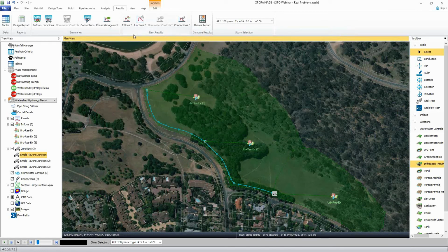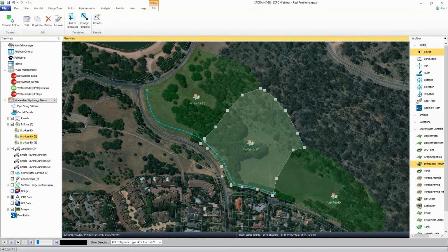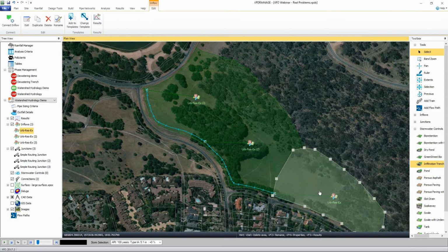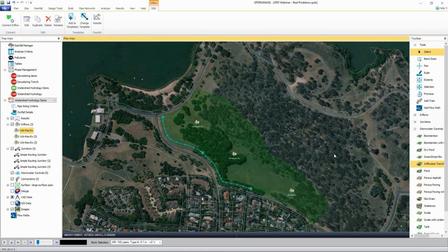We could ultimately compare different phases quite easily. Using this phase report, we could look at maybe existing conditions, maybe just a broad brushstroke of developed conditions, okay? And we could have a very large system with these basic cues of, it's going to take a few minutes to get down through some sort of channel, okay? Add those delays. So really quick to add in basic hydrology without getting into details of there is a pipe or there is a weir at what elevation, okay?